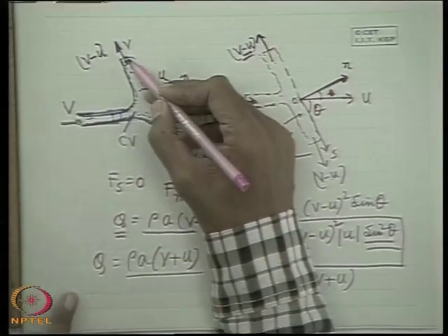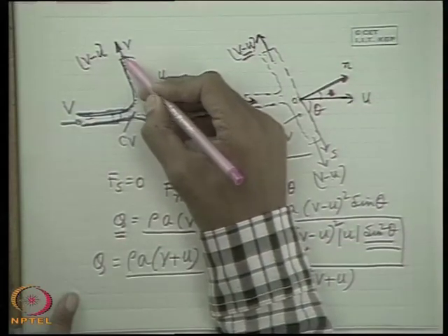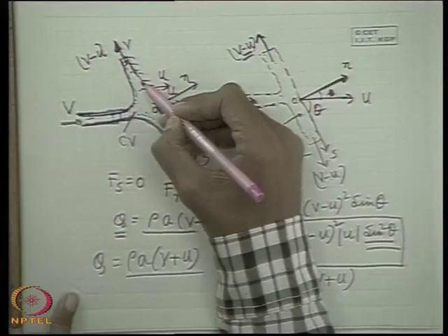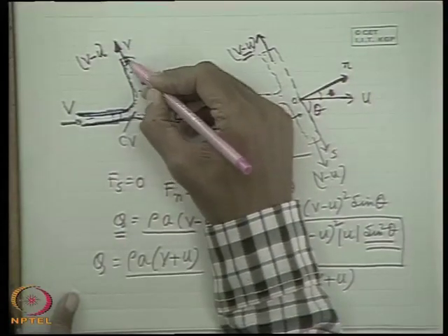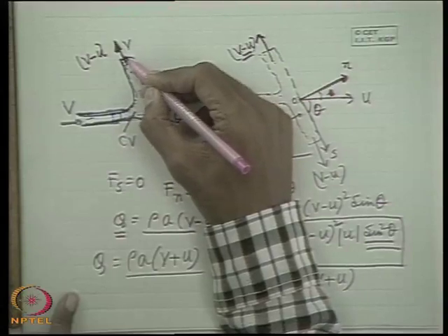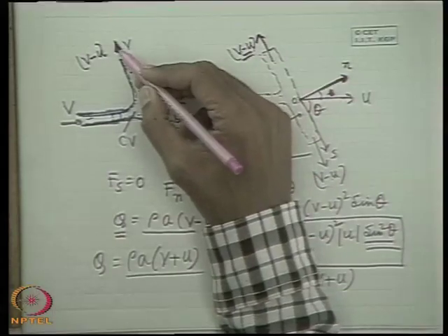That means with respect to the solid, the liquid should always glide along it. So a person moving or sitting at the plate will always see the liquid going out at the final discharge plane, gliding parallel to the surface, and this is the relative velocity.